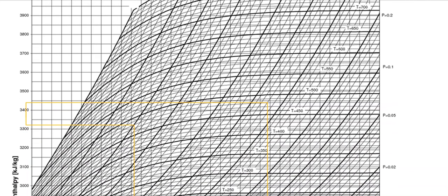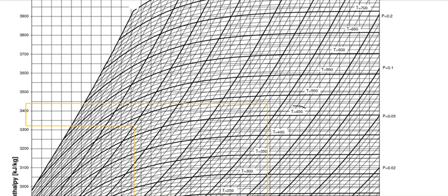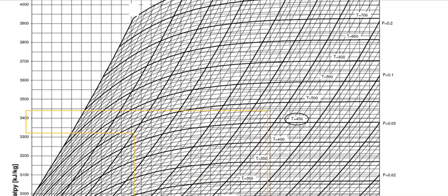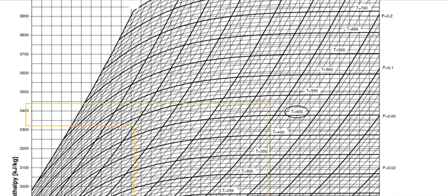Temperature over here somewhere is 450 degrees centigrade. So from 10 megapascal, 480 degrees centigrade, I'm following this line 450 and I'm following this line, so that means 450, 60, 70 and 80. So at this point, this is my state number 1, 10 megapascal and 480 degrees centigrade.